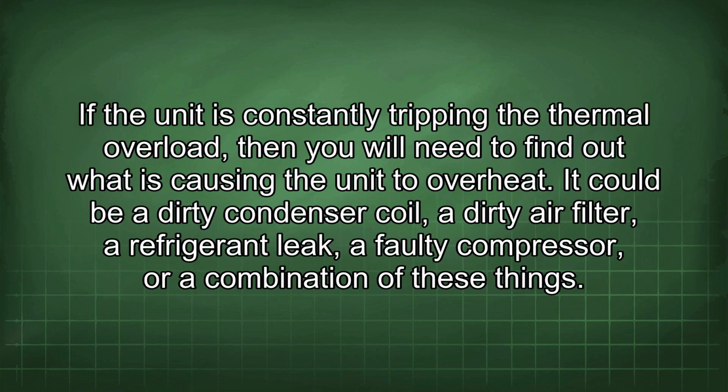If the unit is constantly tripping the thermal overload, then you will need to find out what is causing the unit to overheat. It could be a dirty condenser coil, a dirty air filter, a refrigerant leak, a faulty compressor, or a combination of these things.